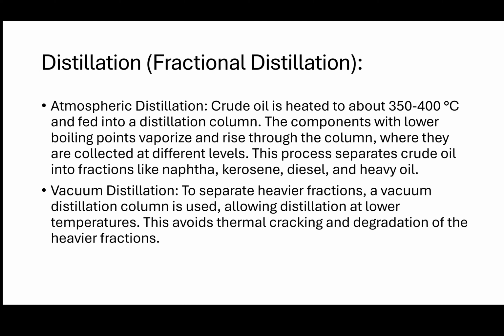Vacuum distillation. To separate heavier fractions, a vacuum distillation column is used, allowing distillation at lower temperatures. This avoids thermal cracking and degradation of the heavier fractions. So if we want to get heavier fractions without breaking them up or cracking them into smaller fractions, we use vacuum distillation.